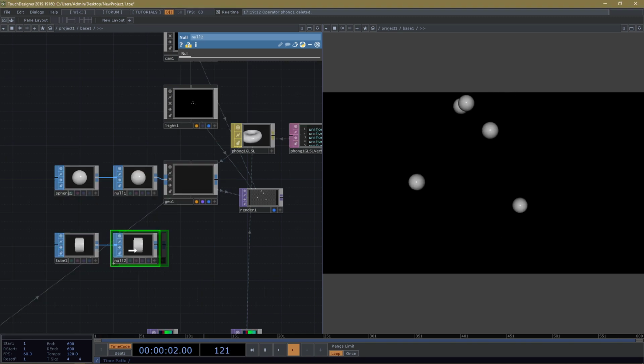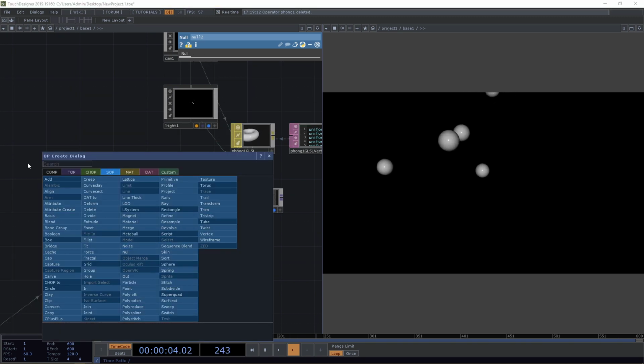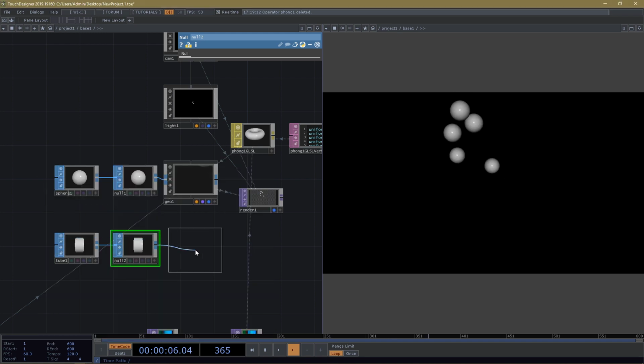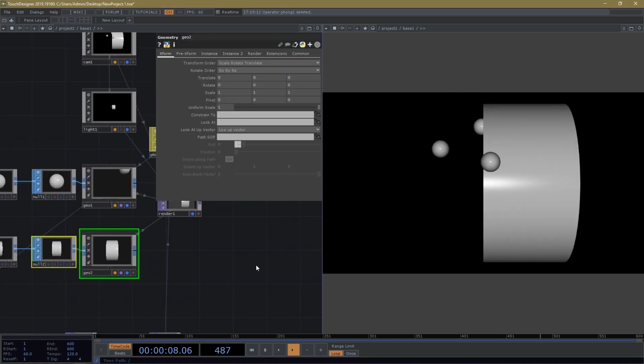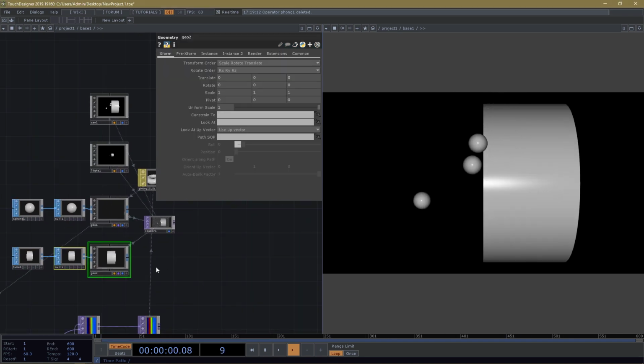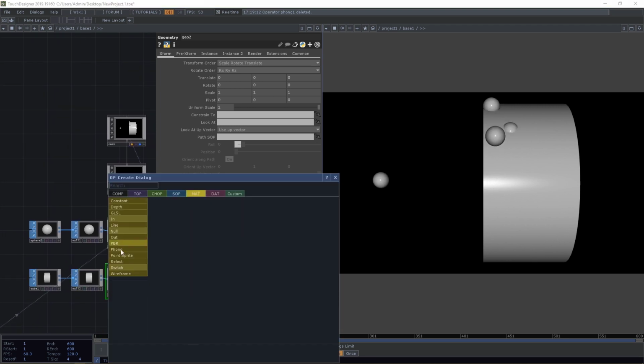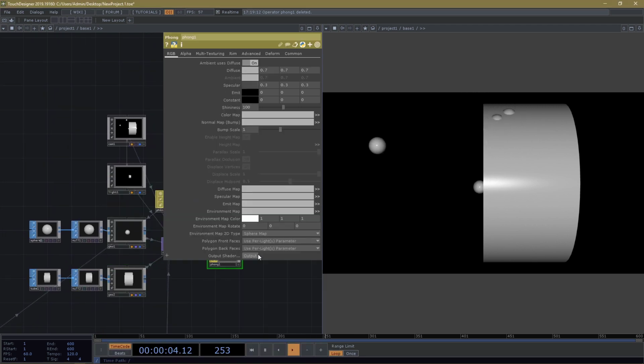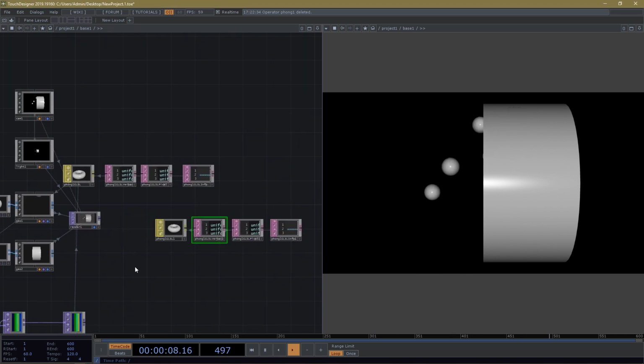There are actually probably better ways to keep track of it than the way I'm going to, but this is by far the most simple and flexible. So put out another Phong shader and the GLSL again. Actually just going to copy that first one because it's got some of what we need.